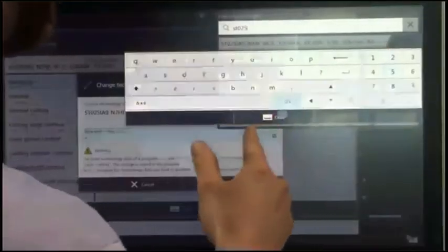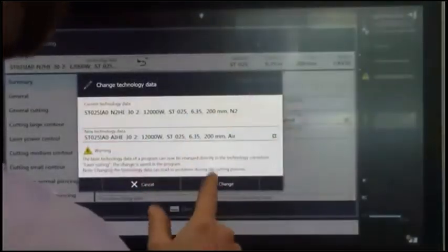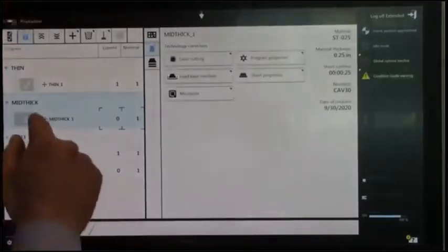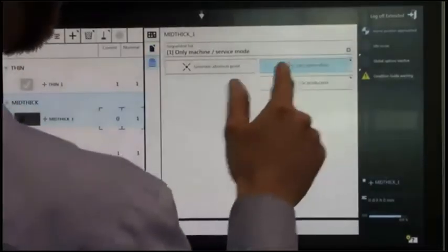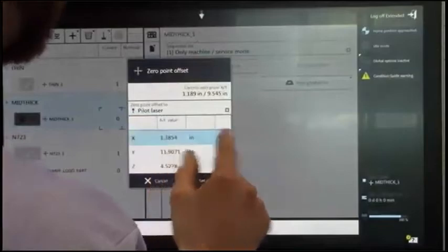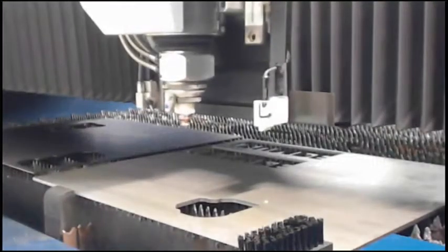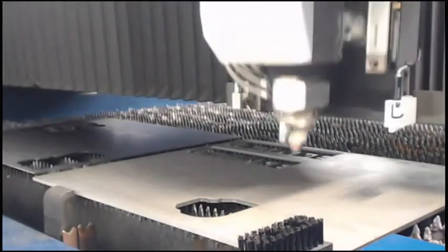All right, so now let's go and use air. So this is, again, going to be a little bit different than the stainless steel, as we're going to employ this special nozzle, our Highspeed Eco nozzle. This is going to be going 450 inches per minute, so it is a little bit slower. That's pretty typical of air cutting with steels, but air is really inexpensive, which is awesome. So this uses 6 bar of air, and again, 430 inches per minute.